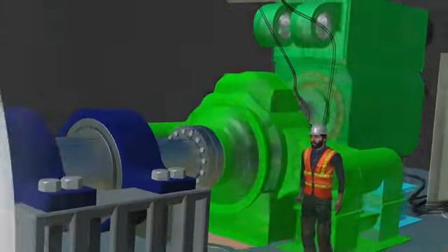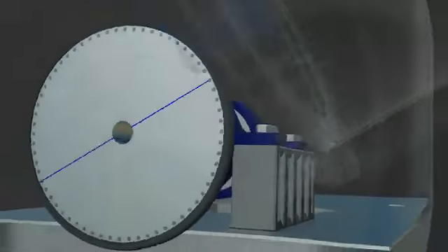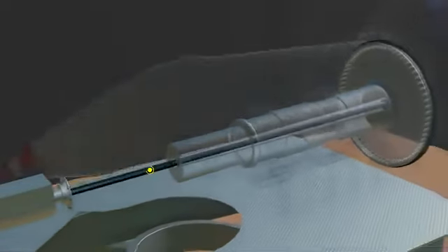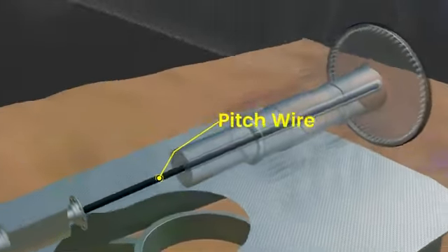A hollow shaft design is employed for the main shaft. This design provides a high strength-to-weight ratio while reducing material usage. The hollow interior also serves as a passageway for electrical wiring and data cables for pitch motor control, creating an electrical and data connection between the nacelle and the hub.